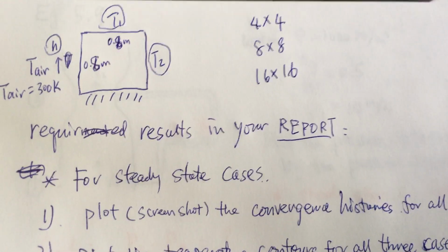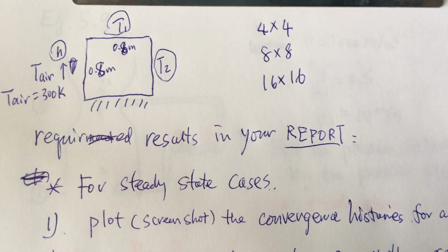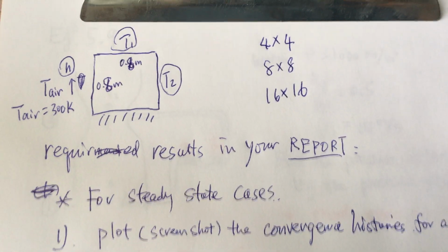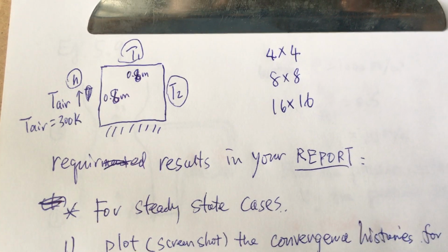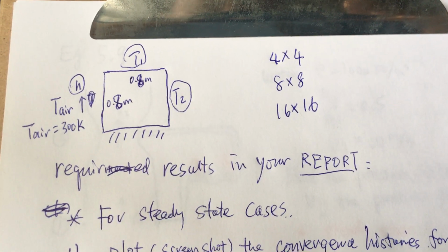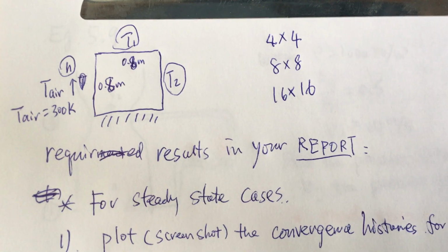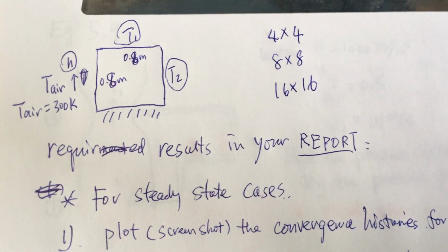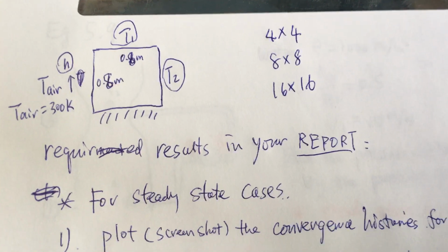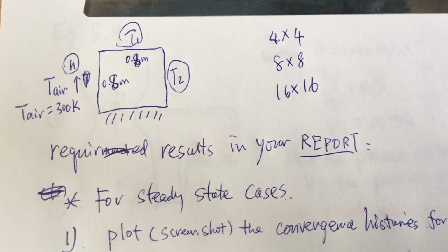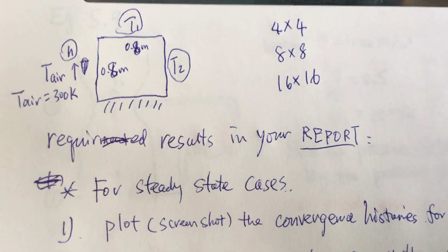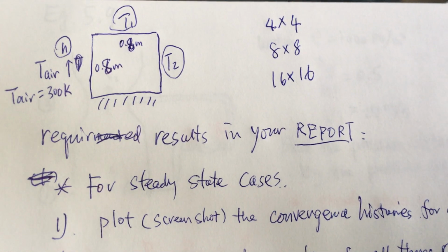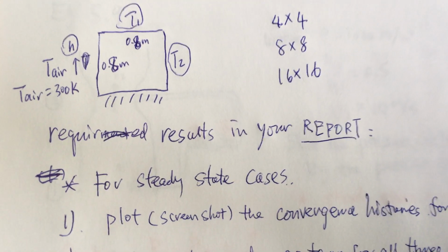By the way, Fluent is actually solving that differential equation, right? The heat transfer problem: initially the general equation is a differential equation, so it uses linear algebra to approximate the differential equation. On every grid point, it will calculate based on the boundary condition, right? When you solve a differential equation, you need the boundary condition.